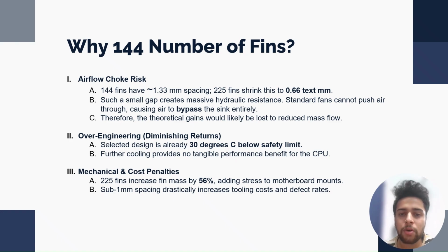Secondly, we did not want to over-engineer our design. The requirement was only to keep the temperature below 85 degrees Celsius, and the present design already keeps it at a 30 degrees margin. So increasing the number of fins was not found suitable and feasible. And lastly, increasing the number of fins also makes the manufacturing of the heatsink expensive. And at the same time, it adds more weight on the motherboard mounts. Thus, due to these reasons, we chose number of fins to be 144.